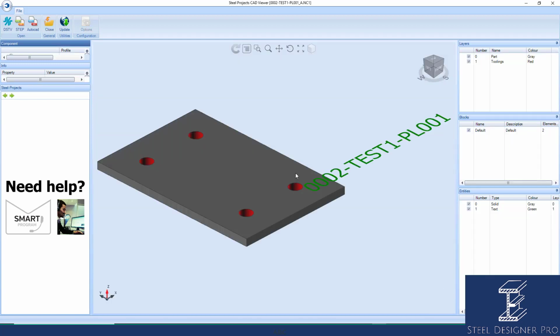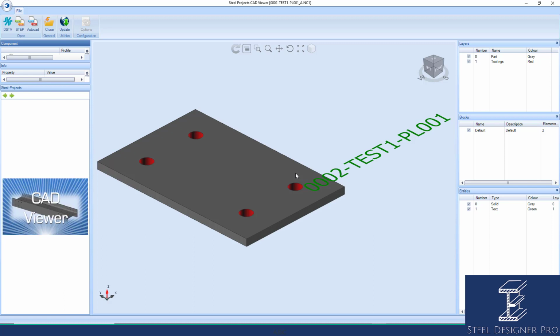If it overlaps holes or it's off the plate or one or the other, you may have to go in there and manually change these. If it's over the top of a hole, you obviously don't want it over the top of the hole. You may have a standard height that you want to engrave the plate to mark the plate, and your text height might have to decrease.